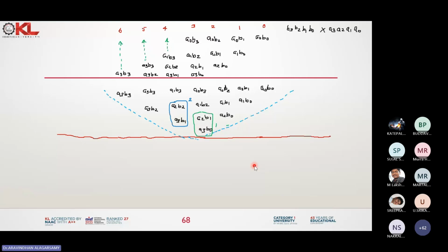I repeat, once you complete this process, it looks like a weird tree structure. After forming the tree structure, we have to construct block segregation. Block segregation means we have to identify the adder blocks. To identify your final adder blocks, we will start from the top of the tree, the upside down one, where I combine these two as a single adder block, and from the left hand side I will select these two as a combined block.